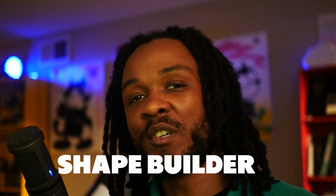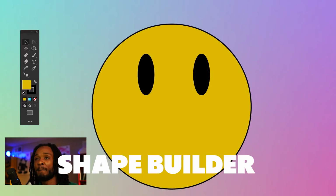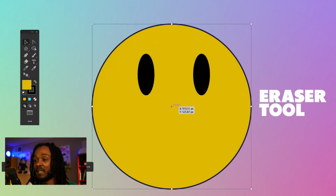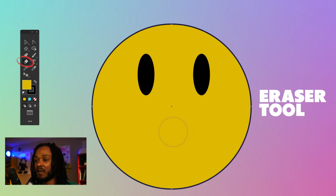Let's say you want to erase portions of any object that you just created. You'll want to use the eraser tool for that. By pressing enter, you can adjust the eraser size to whatever angle and whatever roundness that you need it to be, and whatever size as well. You'll want to select your object, select the eraser tool, and then just click anywhere on the object, and it'll erase that part of the shape.